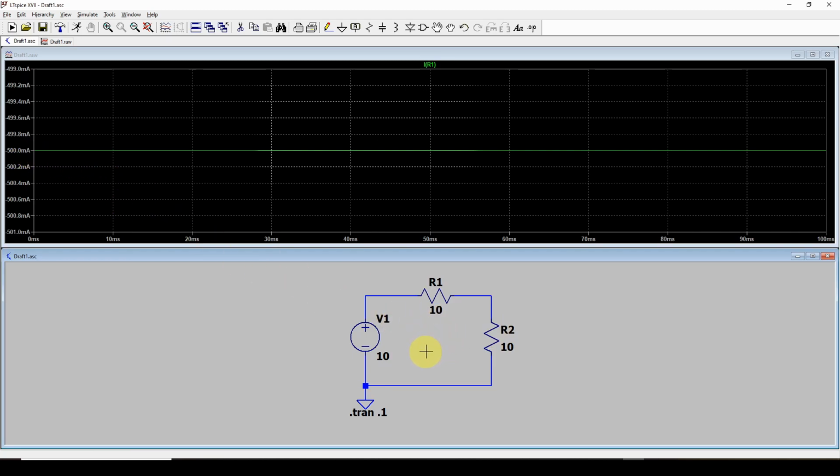So that's why this is such a nice tool if you're learning electricity. You can actually set up a circuit, decide before you run the simulation what you expect the answer to be, and then run the simulation and see if it happens the way you thought it would. The rule of garbage in, garbage out applies. If you put in the wrong numbers, it's going to do a simulation based on the numbers you put in, not the numbers you think you put in. So don't use it as the final answer unless you're absolutely sure of your data. So be very careful.